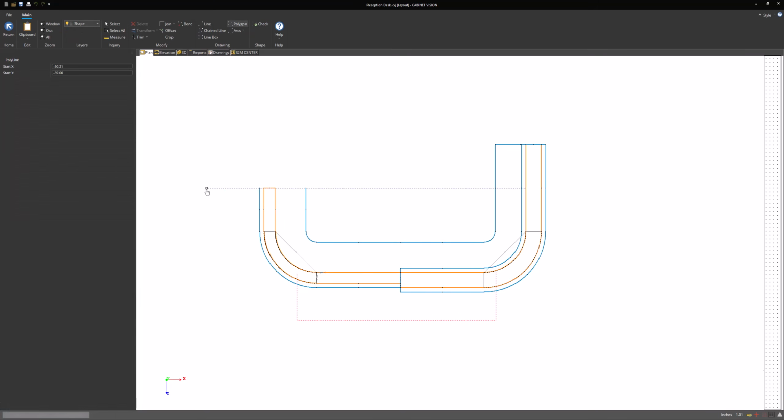And then I'm just going to go to new top and essentially just trace around the CAD that I've already added in. I'm going to build this section in one big countertop, but obviously you might want to include a split in this as well. And then for any arcs, I'm just going to use the bend tool.